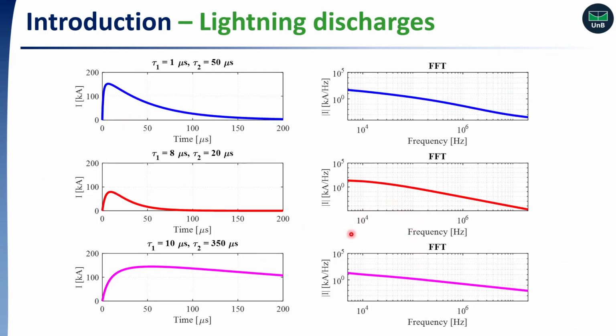The solution for EMI under steady-state sinusoidal conditions is well known in the literature. However, in this work we want to observe the impact of different lightning discharges. This is challenging because we don't work with regular phasors anymore. In fact, we have a current impulse at the base of the lightning channel with different time characteristics, which often result in frequency components of the order of some megahertz, as you can see from the FFT here.